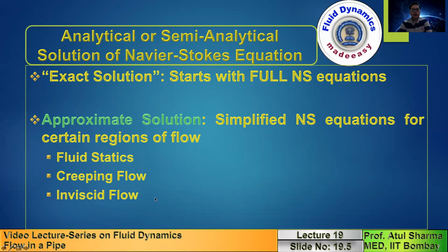There is a separate subject within fluid mechanics called inviscid flow theory, which I'll discuss in the next slides. For considering the fluid as having very small viscosity and incompressible flow, for this class of flow regions, there are certain regions in the flow where the effect of viscosity is negligible. For those flow regions, there is a theory of inviscid flow through which we can obtain the analytical solution.